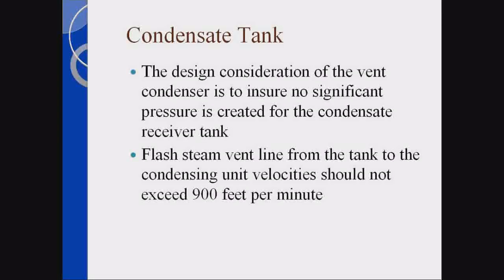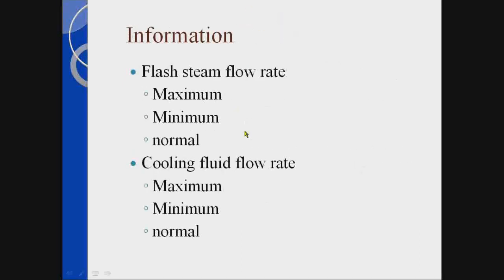The reason we're very specific on that is the flash steam is going to be traveling in an upward flow, and we're condensing the condensate, and the condensate is going to be dropping down through that vapor flow. And we want it to drop. We don't want any velocity to keep the condensate going up into the condenser. It's a very important fact, and a lot of times people forget about that.